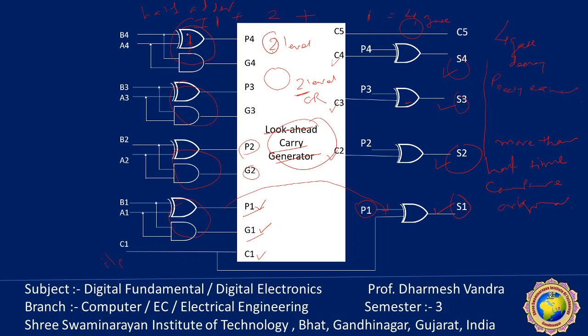The same circuit is also useful for 8-bit or 16-bit adders. For 8-bit and 16-bit adders, this circuit is very important to generate less delay time for fast operation, and power consumption is also reduced compared with the traditional full adder circuit. This is the typical look ahead carry generator, and a ready-made IC is available.